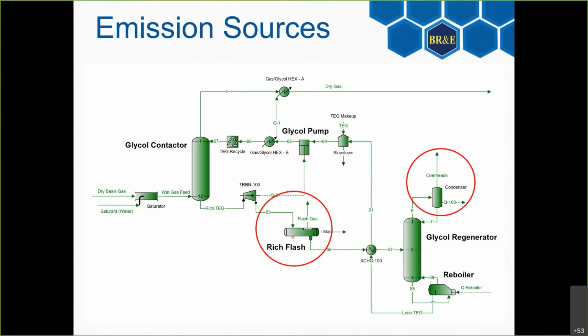So a control device is there to reduce the ultimate hydrocarbon emissions that you're going to be venting. This could be in the form of a combustion device like a flare. It could be a BTEX condenser, something that liquefies the hydrocarbons. Those kinds of control devices, we feel that if the EPA is comfortable with us estimating what that gas flow rate is and that gas composition entering that kind of control device, well, if we're able to do that, that means that we are able to simulate properly the whole facility.